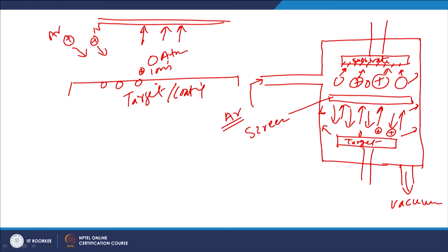So, these are the different constituents as far as the sputtering process is concerned. And for ionization or for having the high energy ions, we may use diode or the magnetron, and high energy ions can be generated using the argon or the nitrogen gas mixture, which will be filled in the chamber. So, these are some of the features as far as the sputtering process is concerned.